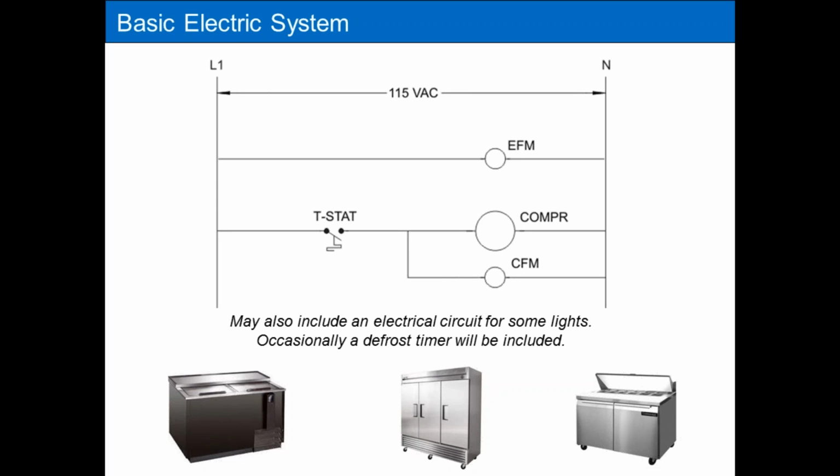And that's good to know, because when you go up to the unit, when you're beginning your diagnosis of what the problem potentially is, you want to do a visual inspection, and one of the things you're looking for is the evaporator fan motor running or not. If it's not running, it tells you something that's happening, and if it is running, well, that's good. It's supposed to be running.